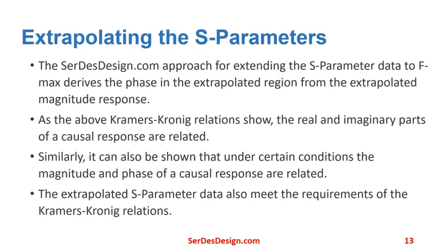Extrapolating the S-parameters. The SerDesDesign approach for extending the S-parameters to Fmax derives the phase in the extrapolated region from the extrapolated magnitude response. As the above Kramers-Kronig relations show, the real and imaginary parts of a causal response are related. Similarly, it can also be shown that under certain conditions, the magnitude and phase of a causal response are related. The extrapolated S-parameter data also meets the requirements of the Kramers-Kronig relations.